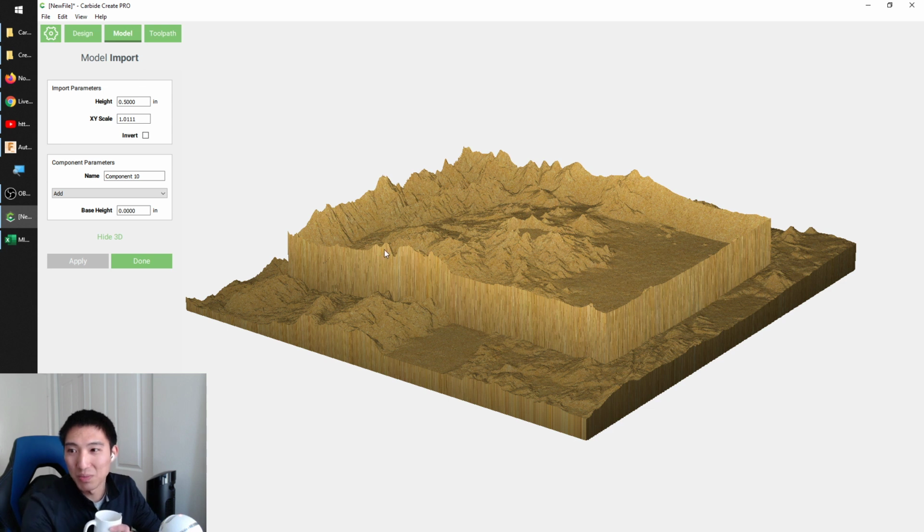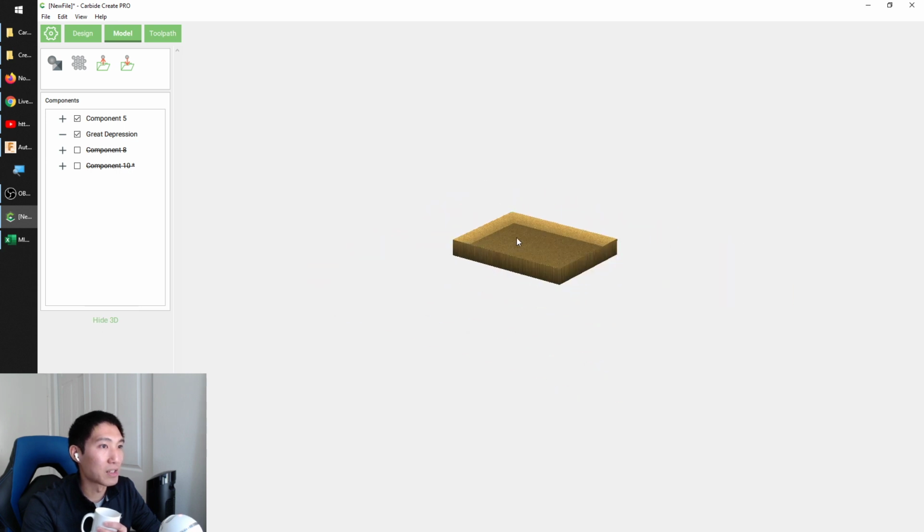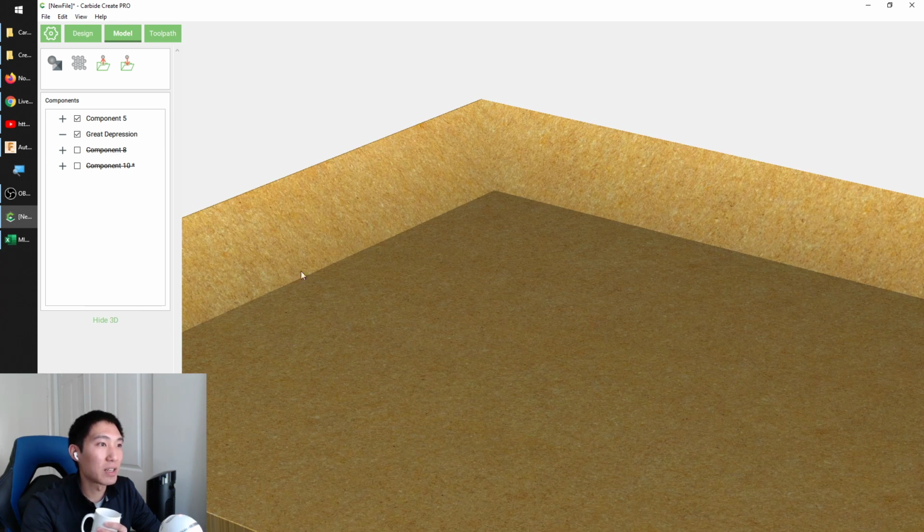The world's your oyster. The ball end mill will not give you a sharp corner, but depending on the diameter of that cutter, it'll get pretty close. If you want a sharp corner, you could use a flat end mill, but then you need to machine it across in one direction, and then also the other direction, because a feature like this has a sharp corner on the X, positive and negative X side, and the positive and negative Y side.